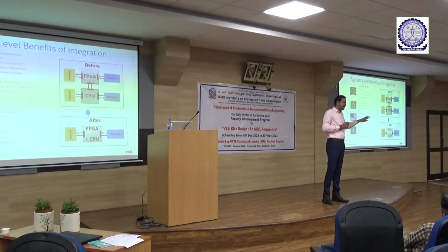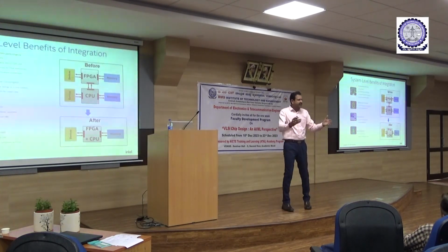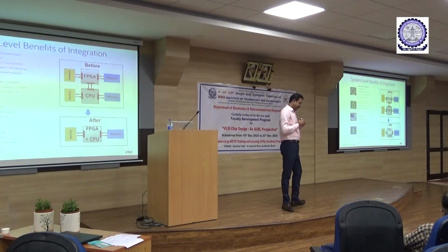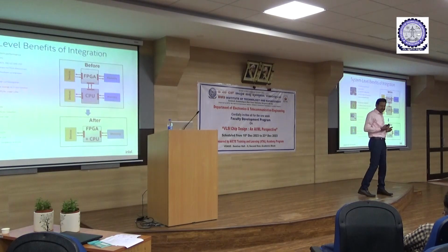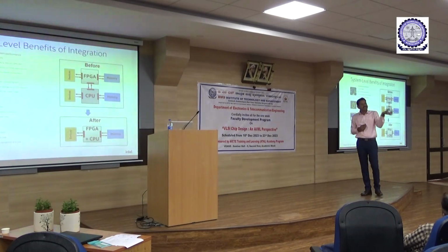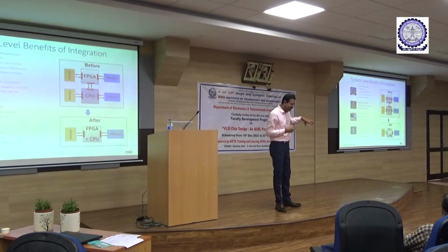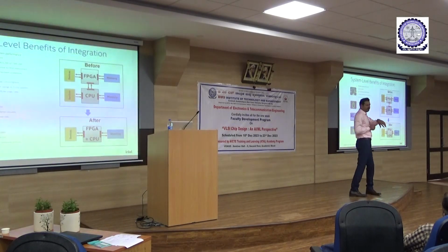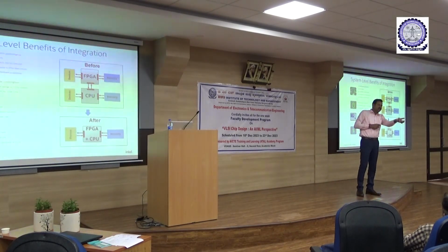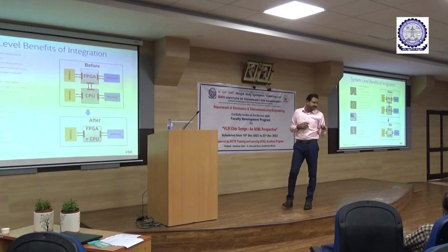If you say, I want to do only FPGA, you can still do that. I want to do only software, we can still do that. But we can also make communication between the FPGA and the processor. Now you need to create an embedded system. Earlier, what was the situation? What is available on the FPGA side? You have one UART, and only that you need to depend on. You will also have some other peripherals in the processing system, in the hard processor system. So you can use those components also to create an embedded system. So you can create a custom embedded system, right?